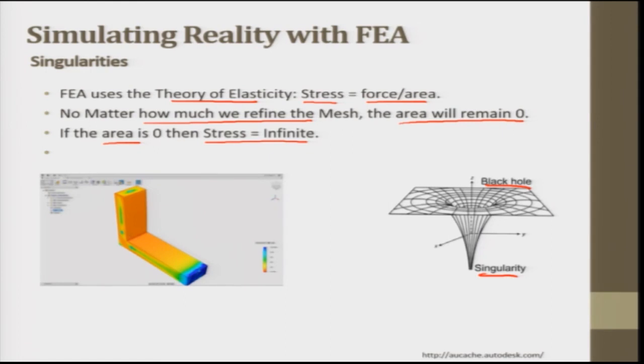There are certain errors that could happen while we are conducting this FEA analysis, finite element analysis. The modeling errors due to simplifications: we try to model the real world and yet are not able to do it 100%. More simplification sometimes leads to error. Sometimes discretization errors that result from the creation of the mesh, where the division of the mesh is not proper.